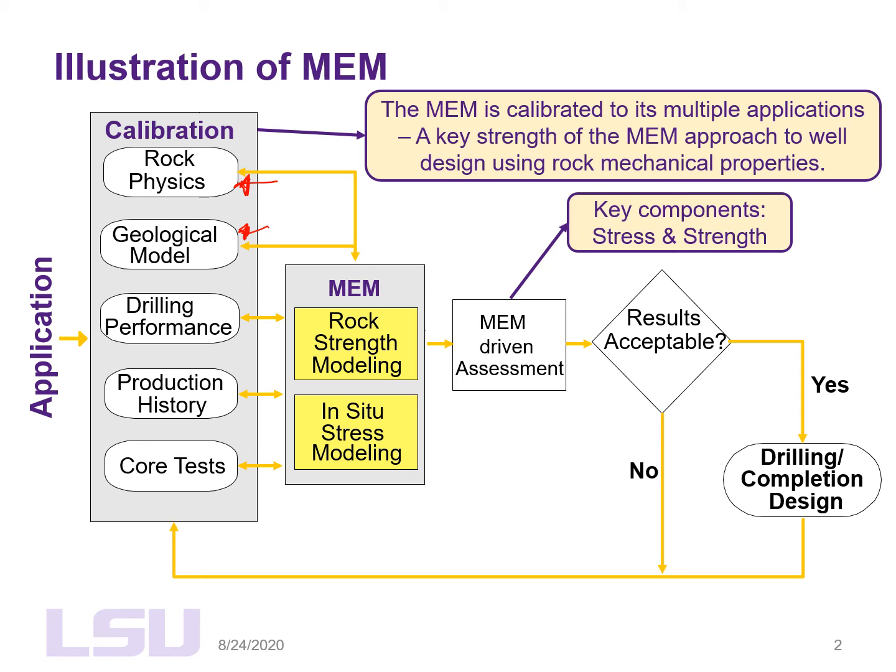In the mechanical earth model, we have the mechanical state of the rock, which we discussed in the previous slide. So using this mechanical earth model, we start to drill. And while we drill, we obtain new data, right? So we can validate our model and we can calibrate the model to honor the newly observed data. So we update our model with our data.